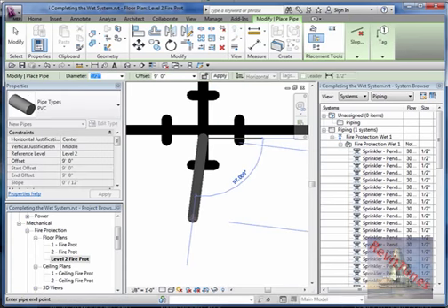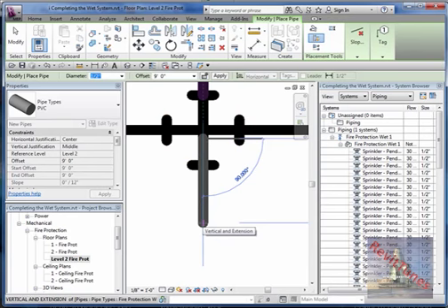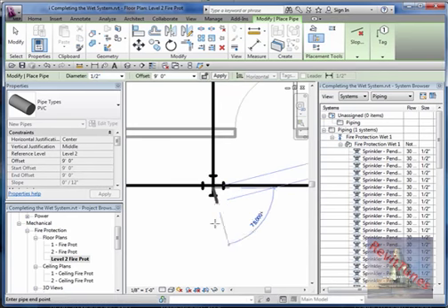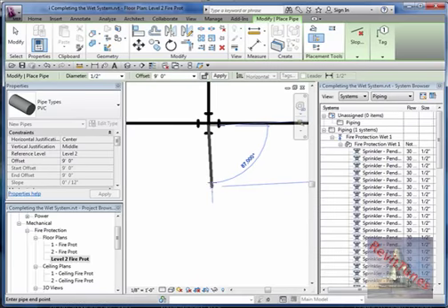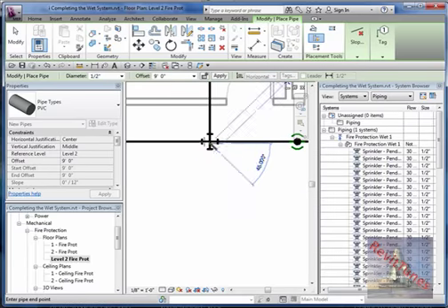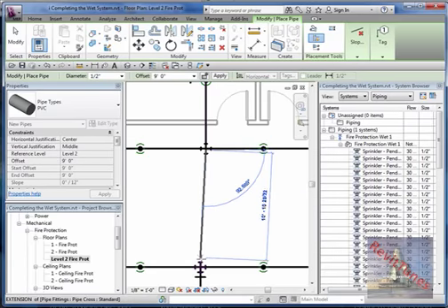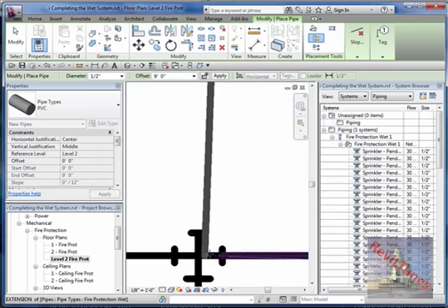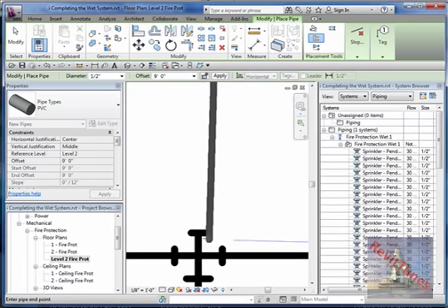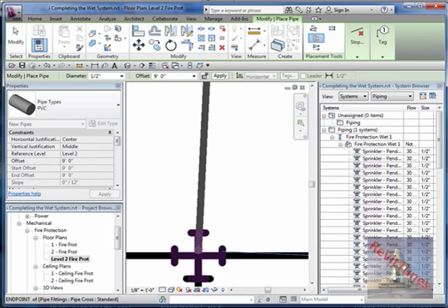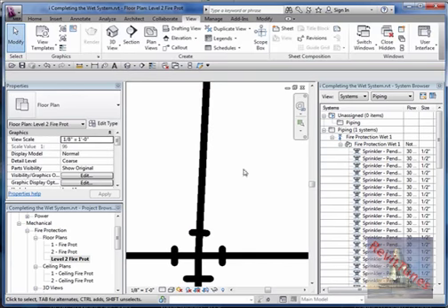I could hit the key tab, the long key tab. When you hit tab, it grabs the height of this connector. At this point, because I'm using only one height, it might not be necessary, but get used to hitting tab before you start doing a pipe, so it grabs the height of your connector where you begin your pipe.